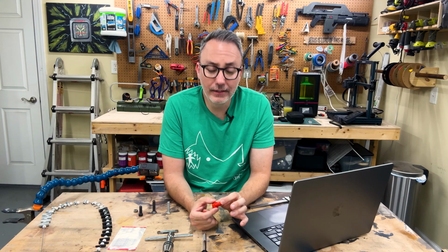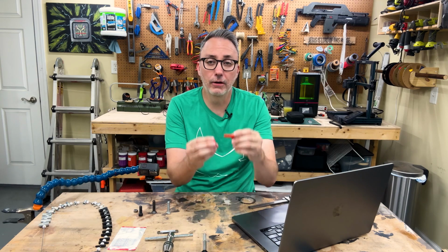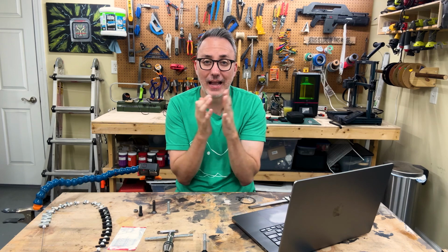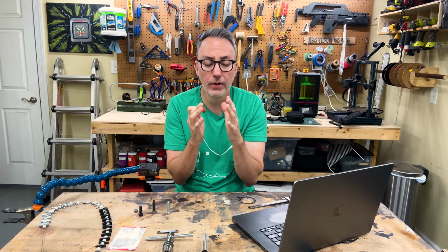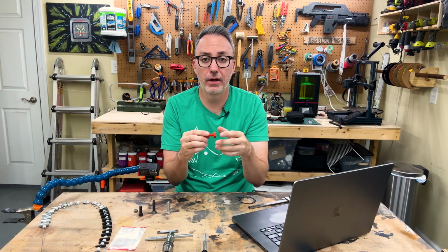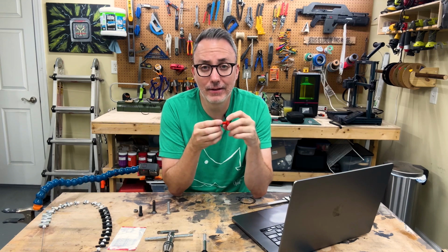All right, let's talk about 3D printing. If I were to 3D print a bolt and a nut with just the settings that Fusion 360 uses, there would be too much interference. They would not screw on, because they are printed exact. There's too much friction. There's no way for them to actually screw on because they're taking up the same space, right? So what we have to do when we're 3D modeling, and it's really annoying, and I wish Fusion 360 would add a setting for 3D printing, but they haven't yet.